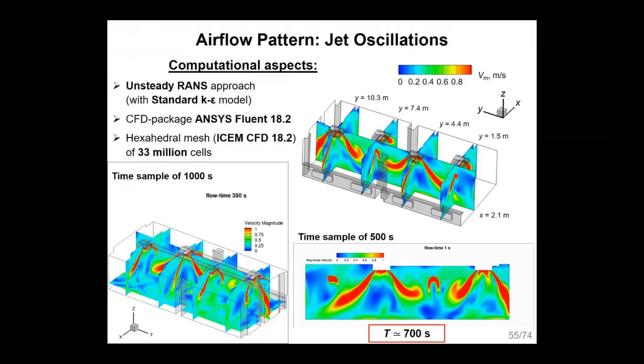The flow with the numerous jets is unstable, and we were not able to perform large eddy simulation modeling for this complicated problem. These are just unsteady Reynolds-averaged Navier-Stokes approach data. But even this RANS modeling cannot obtain a steady-state solution. The jets oscillate and their pulsations are well pronounced with large amplitudes and relatively low periods.